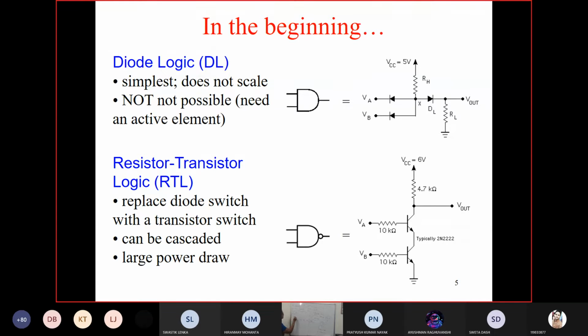0 volt means what? It is no bias. So open circuited only, this one. Second one, then afterwards, this is reverse bias, open circuited. Then what happened? This is only the diode. So this is positive, right, 5 volts. So will this work or not? Yes, it is forward bias and you will get an output.